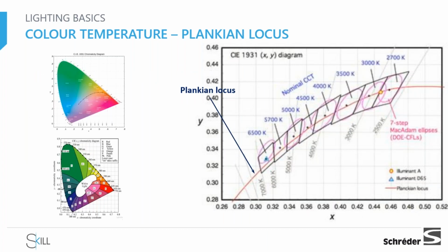Once we are representing a specific color temperature, and we will come to speak about it, a white color with 3000 Kelvin or a white color with 4000 Kelvin, we are representing an area, not a single point, but an area surrounding it, because it will also be very difficult in the process of producing the LEDs. It will be very difficult or impossible to have 1 million LED chips produced with 100% the exact temperature in degrees. Always we have an acceptable variation from a reference point.